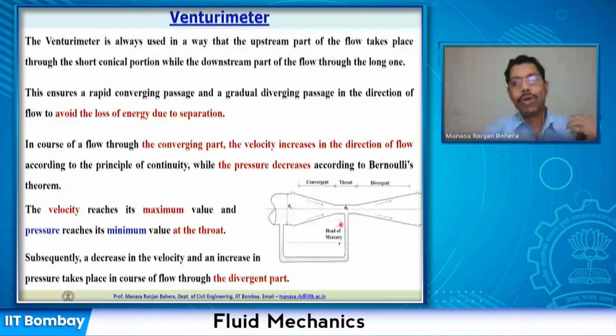All right. So now to get that, we have these two sections. We have already understood that the energy is going to remain the same at both the sections. The overall energy is going to remain the same, and we have already said that the losses are going to be very, very small. Assuming that the losses are really small, we can now equate the total energy at these two locations by applying Bernoulli's equation.